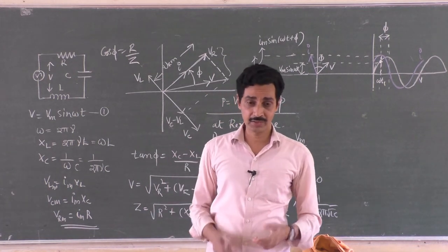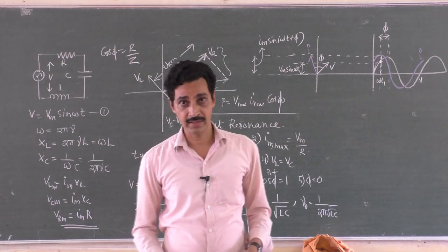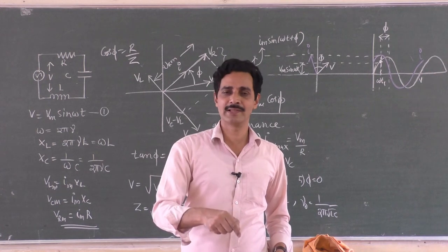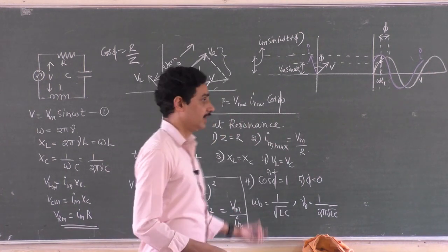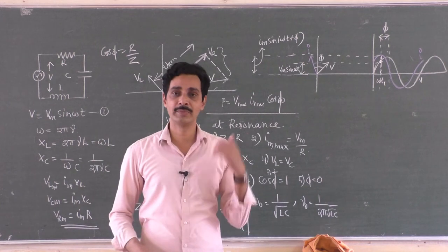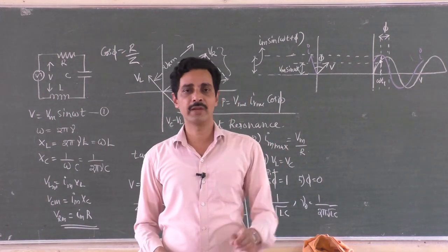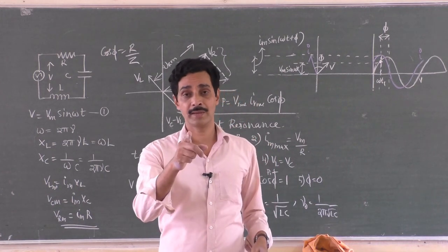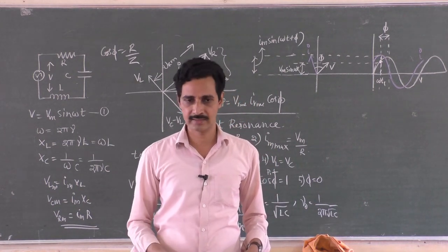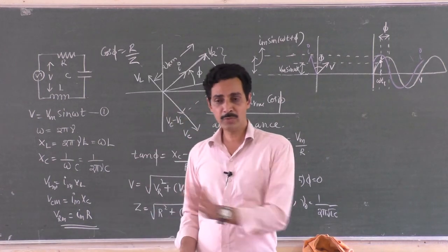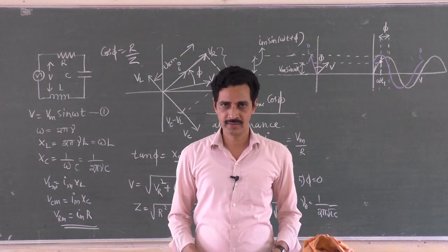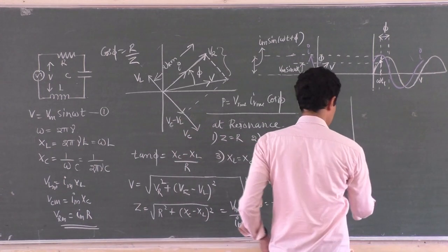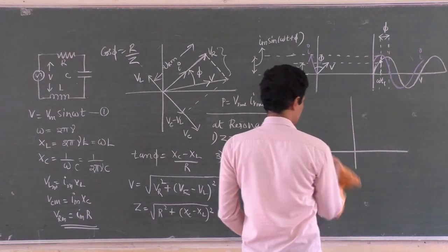That series resonance circuit has its own natural frequency. If you set the frequency of that AC to that particular resonance frequency, which is given by this equation, then only the current flows in the circuit and the current will be maximum. If you set a frequency, number of cycles repeated per second, just below the resonance frequency, the current decreases. That is because of the trouble given by the capacitor. It gives the highest reactance. If you set the frequency just more than the resonance frequency, again the current drops. It will not be the highest value. So if you draw a graph of current versus frequency, then you get a graph like this.